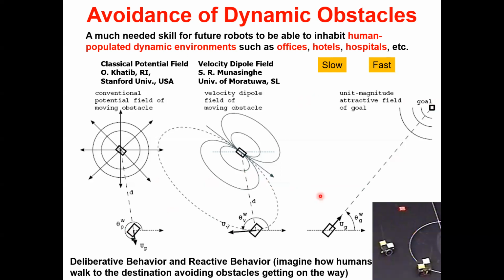Avoiding collision is extremely important in the short run, but it's also important to achieve the goal in the long run. So this is a long run objective. This is the short term defensive aversion of the collision. When you combine these two together, you can generate an obstacle avoidance algorithm, right? And it works. When there's an obstacle, you move away from the obstacle, and when there's no obstacle, it tries to reach the goal, and these two work together at all times.